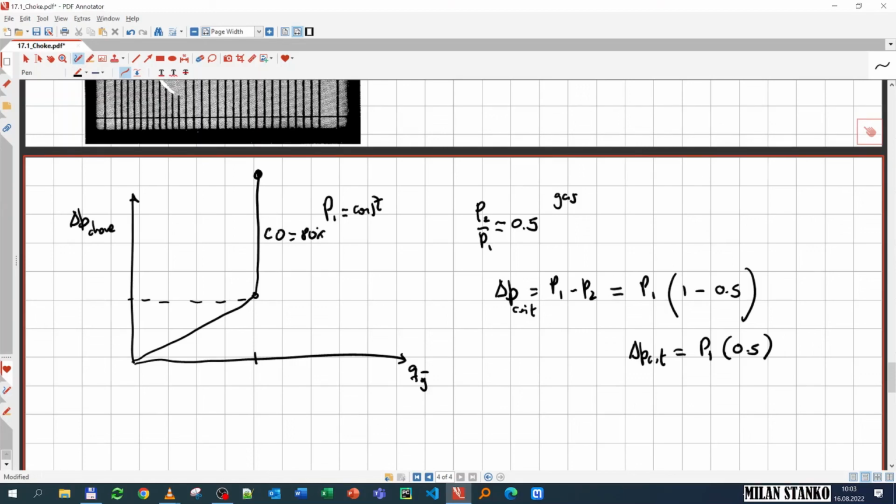And now we simply close it, and then we're using 60%. Intuitively in these regions, you might say it takes the same delta P, simply drawing less rate. So the curve at the lower part is essentially going like this, also from 0, but for the same delta P, because the choke is more closed, it's going to take less rate. But what occurs with the point of the critical conditions?